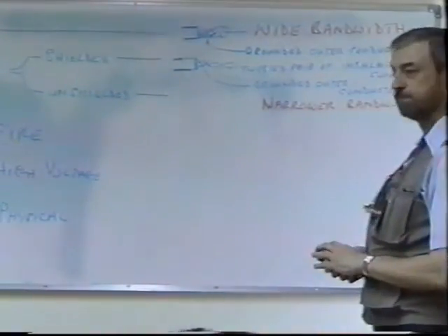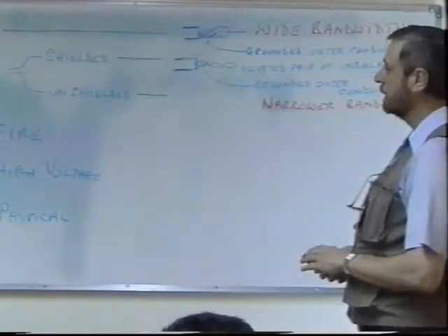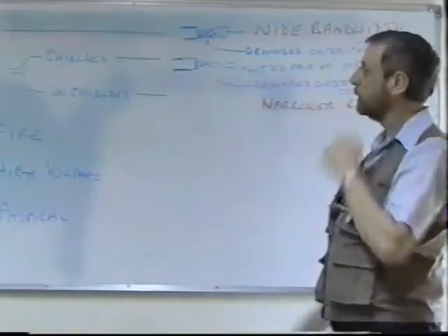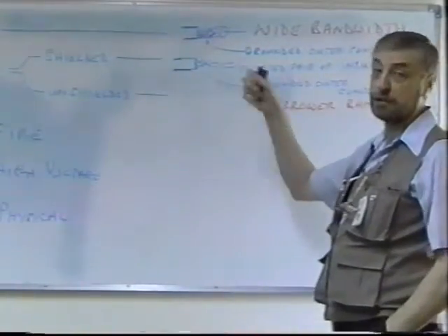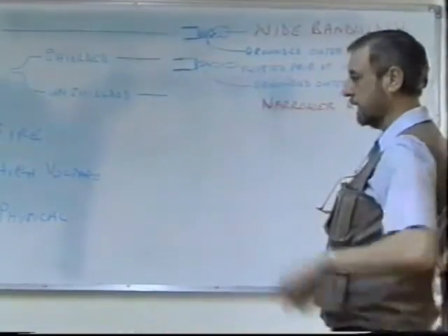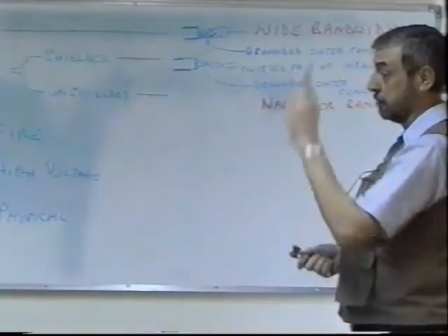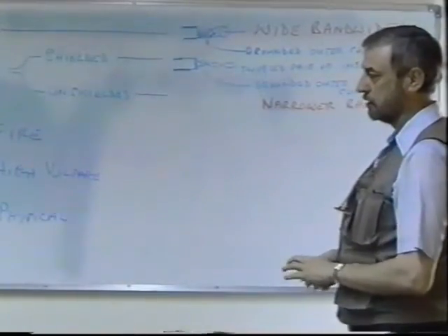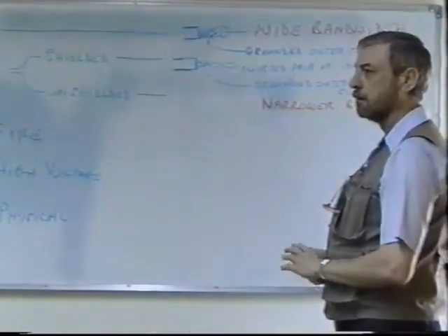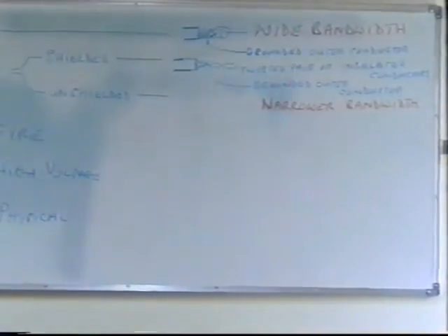I think twisted pair comes in 2 pair or 4 pair. Yes, that's very true. Usually when they make this twisted pair, the IBM standard, they use 2 of these twisted pairs, and they also use some extra conductors to carry some extra signaling in the same thick cable. We have some examples of twisted pair upstairs which I can show you, but I don't have any here. I don't think there's anything here of the shielded twisted pair anyway.